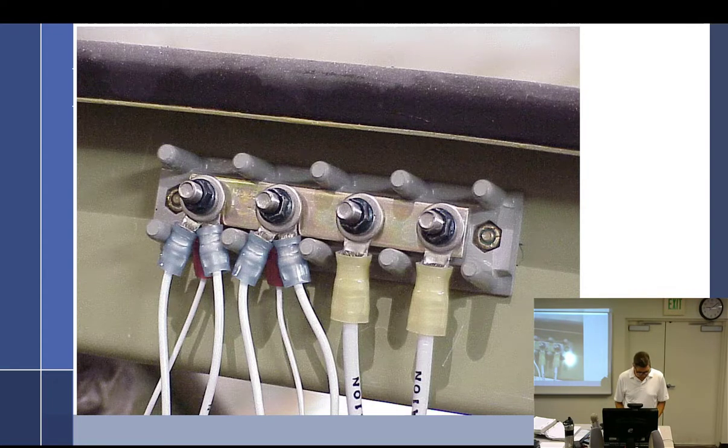And check terminal strip to make sure the studs do not rotate. So these studs are sunk into this phenolic block here. Phenolic's like a plastic stuff. Or they're bolts from the back side where the bolt heads are captured. So those studs should not turn.